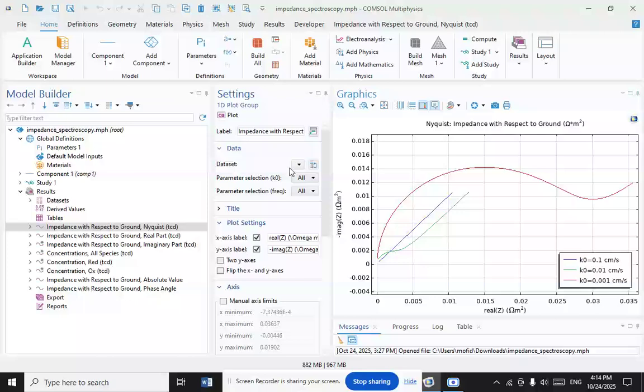On the other hand, in practical applications, the lowest frequency limit is often at 10 to 100 microhertz, as the time required for a measurement at these frequencies is very long. For example, at 10 microhertz, a single measurement takes 1 divided by 10 to the minus 5 hertz, which is equal to 10 to the 5 seconds, which is equal to 27.8 hours.